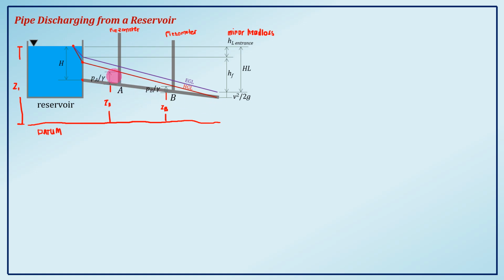Okay? So the certain drop on your EGL after this entrance is the head loss due to friction in your pipeline, the friction between the walls of your pipe and the fluid that flows. So we call it hf. We have the equations for hf from last meeting: the Darcy-Weisbach, Manning's, and Hazen-Williams equations for the major head losses in pipelines. So this is what contributes there.